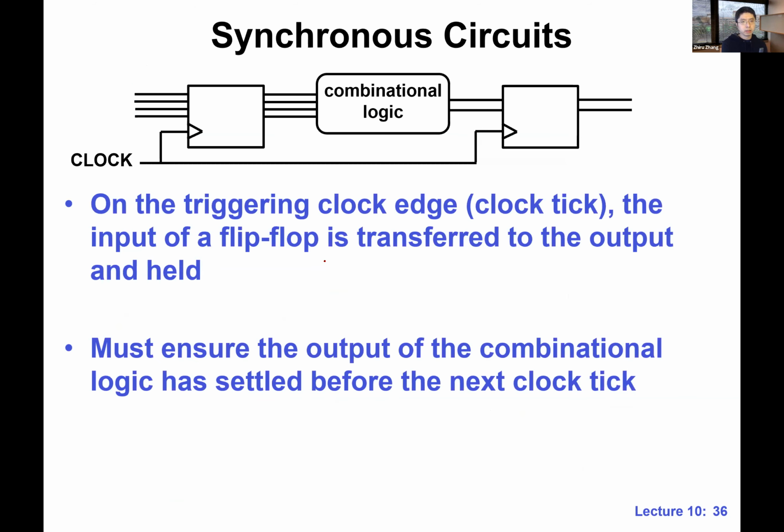All right. And this is an important concept. It's called synchronous circuits. We are using synchronous circuits in our class, which means that the whole circuit is synchronized by a clock. We have many sequential logic, many complex logic, all running in parallel.